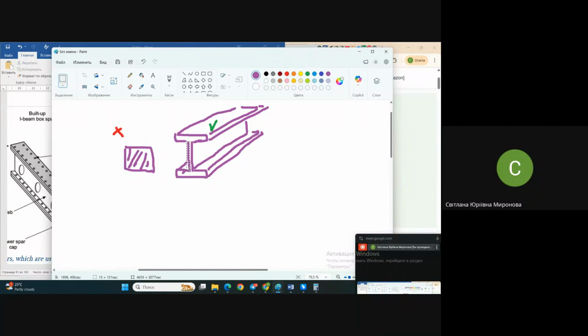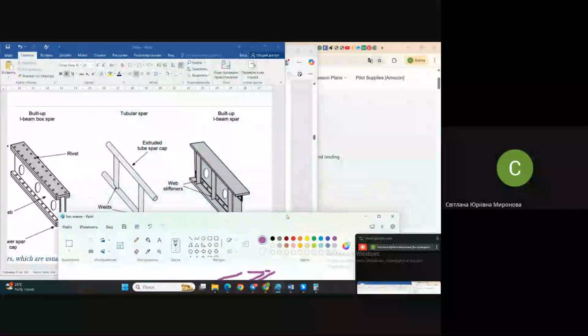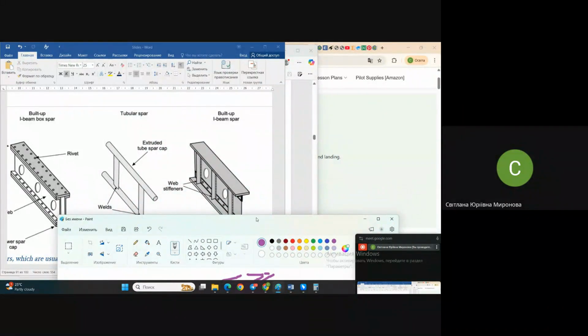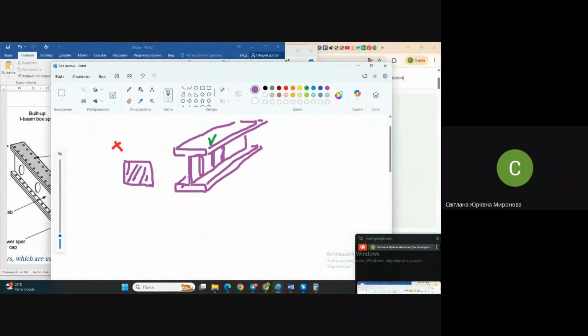Some portion of material we replace, thinning the web, but the same material we place here in the form of additional transversal elements, these struts, like little ribs in the spar structure, as you might see here. And in this case, it became even more stiff.